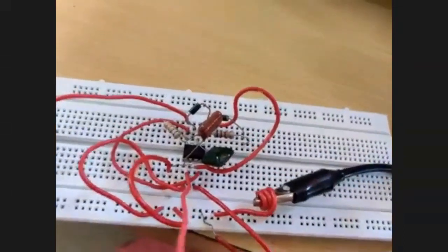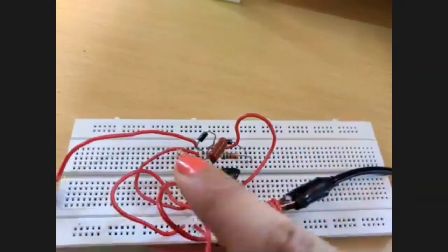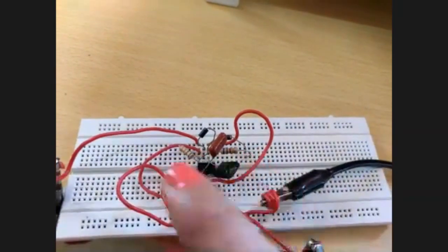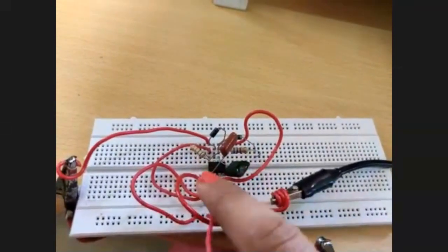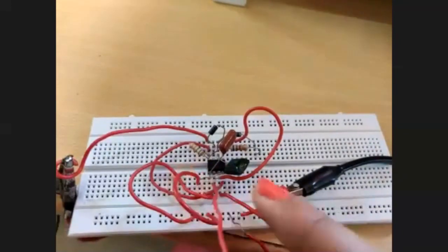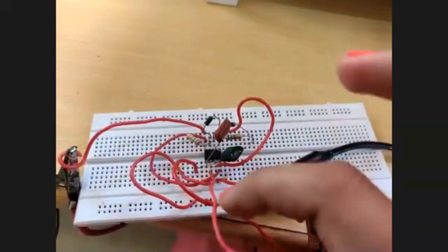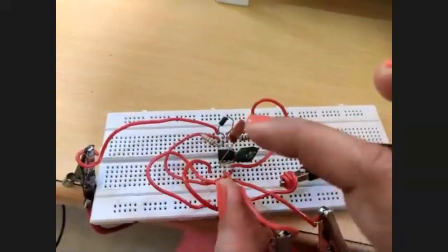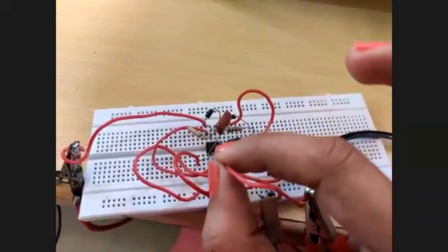So here you can observe we are using two equal resistances, which I already told in the design only. Two capacitors of 0.1 and 0.01 microfarad are connected to the 555, a diode is connected, and we are taking the output across pin number 3. Across pin number 2 or pin number 6, you can observe the variation of the capacitor. Either the charging or discharging signal can be viewed across pin number 2.